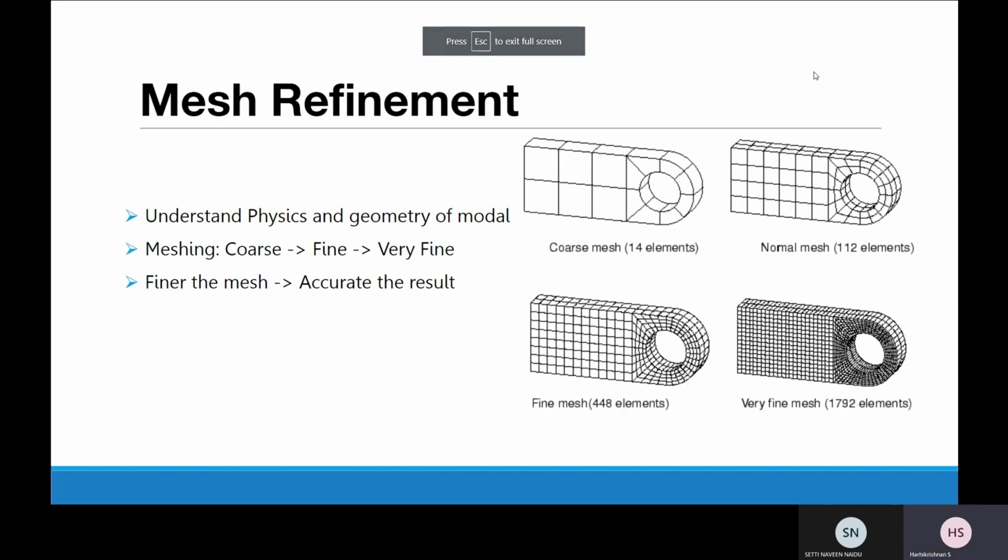So we talked about what is here. One of the important aspects we have to consider is the density of the mesh, which can be altered based upon how complex or simple a simulation is needed. And a good finite element analyst starts with both an understanding of the physics of the system that is to be analyzed and a complete description of the geometry of the system.